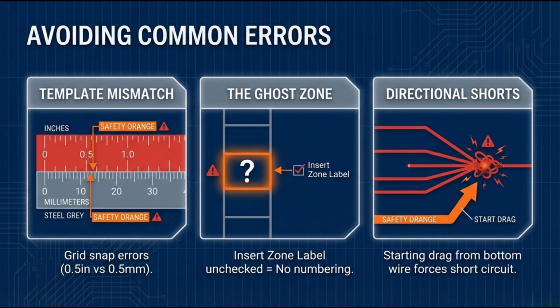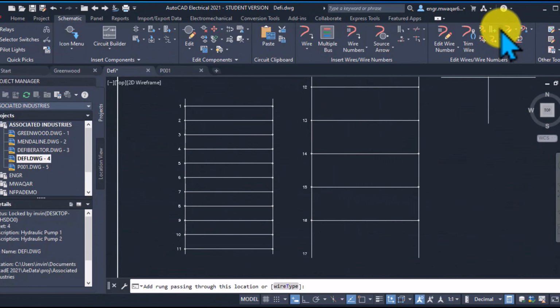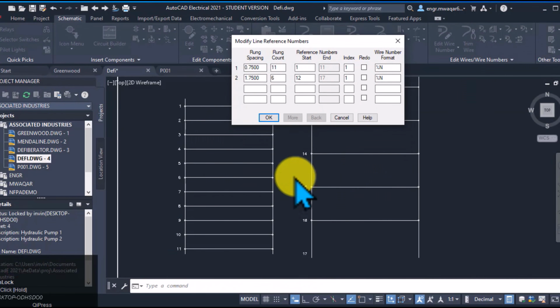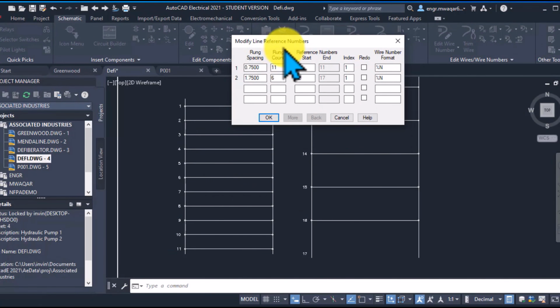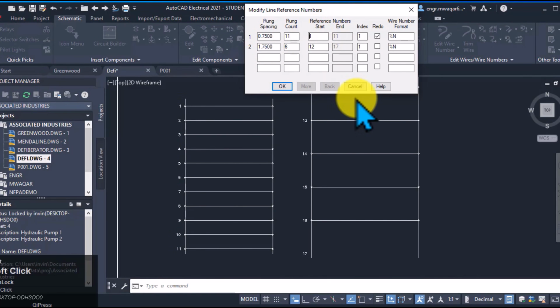You're cruising along, you get down to rung 15, and you suddenly realize you need to put in a field device that is physically quite large, maybe a massive transformer that takes up 3 full inches of vertical space on the drawing. Right. Now, if you just keep the standard ladder with all the rungs drawn in, you are going to have horizontal wires running right through the graphic of your transformer. Which just looks terrible. It looks sloppy, it's confusing to read, and technically it implies an electrical connection that doesn't exist. Exactly. So how do you fix it without messing up the whole page?